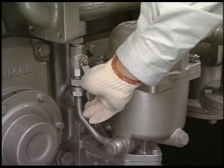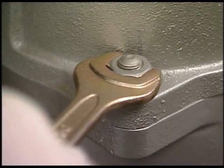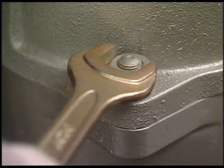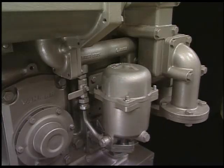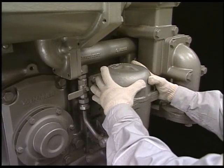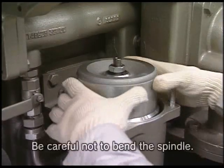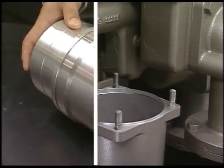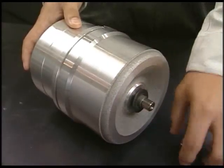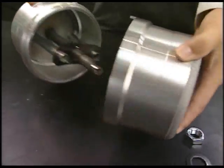First, close the valve on the inlet side of the bypass strainer and remove the tightening nut of the main body cover. Detach the main body cover and remove the rotor assembly inside. Loosen the tightening nut of rotor cover and disassemble the rotor.